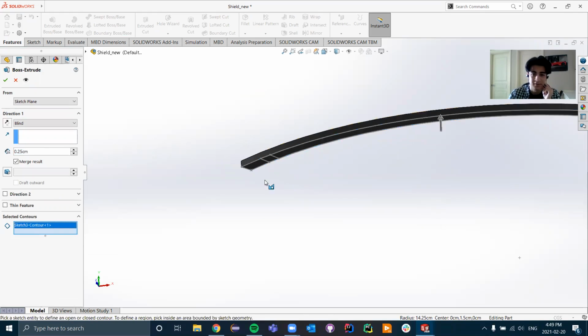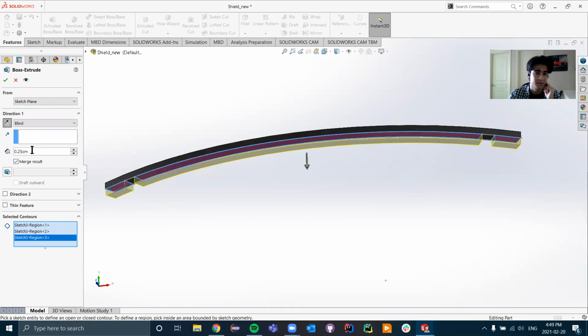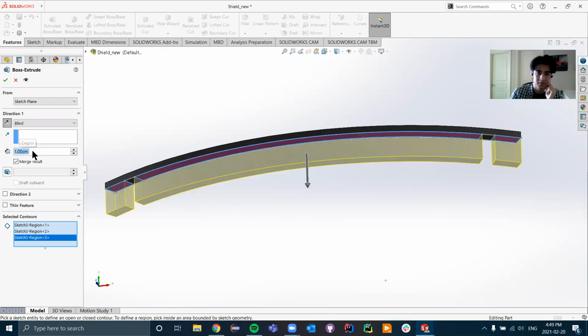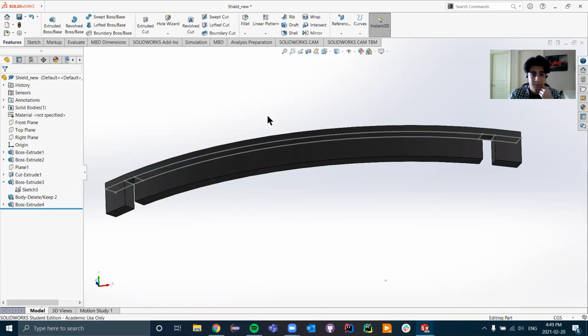Okay, delete that selection. And we'll select everything around these slot holes. And if you remember, it was a 1 centimeter thick extrusion. And now we can actually merge the result because all we have left is the new part that we created. So I'm going to press OK to that. And as you can see, it's one solid body.